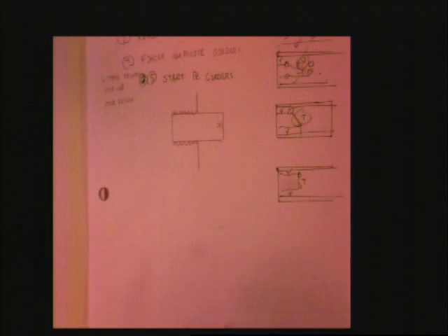So, composite beams. When we work composite beams problems, what is a composite beam? Concrete and steel. Concrete slab, steel girder. They're hooked together by Nelson studs, right? Okay? And there's two situations as a structural engineer that happen when it comes to design. The plastic neutral axis is either in the girder or in the deck, right? How do we decide where it's at?